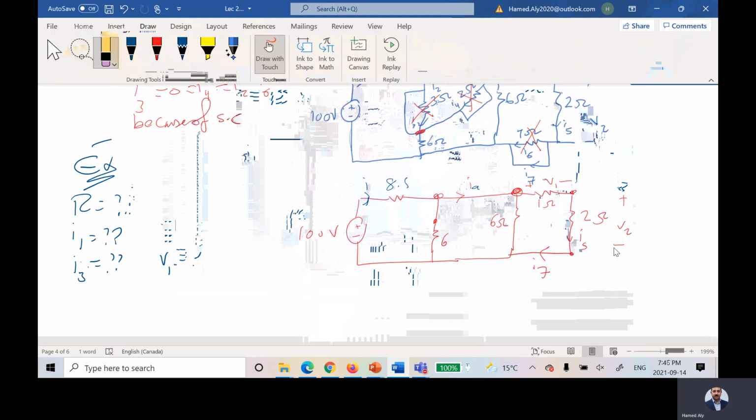Okay. Then I will say summation the voltage for each loop is equal to 0, and summation the current for each node should be equal to 0. But just 1 second. When I gave that problem to my students, I put them the connection in parallel and series. And to solve that problem, you have to calculate R total and then find I total and then start distributing the current by using current divider and voltage divider. So solving that problem depends on current divider, voltage divider, and R total. But I can solve this problem by using KCL and KVL as well.